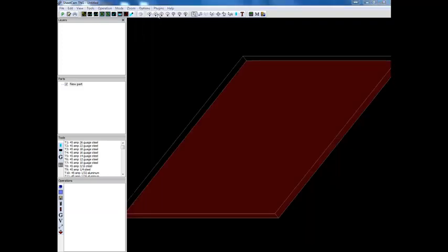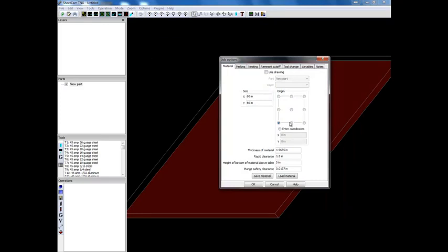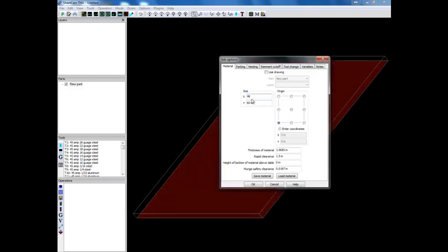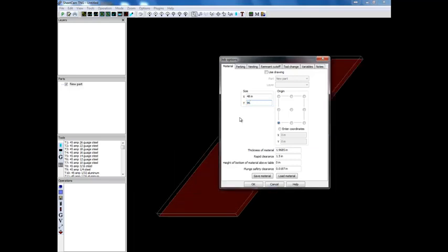Once you have done that, your next step is going to go into options, and you will go under job options. Here you will set the size of your material. Generally I will set this to the main size of my table. So if it's a 4x8 table, 48 by 96. When you do this, you want to make sure your origin stays down here.